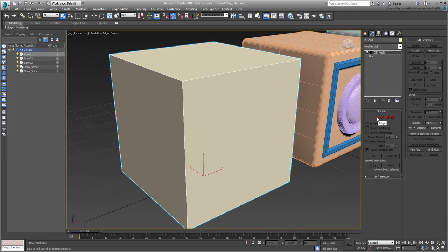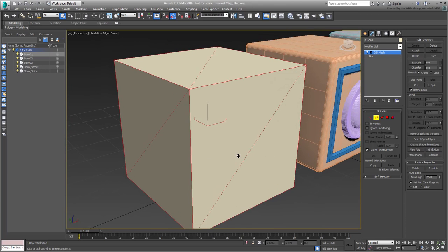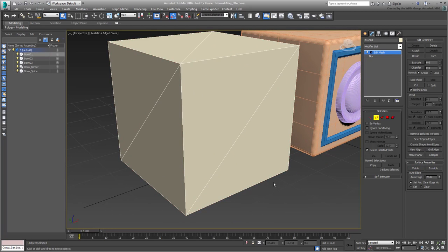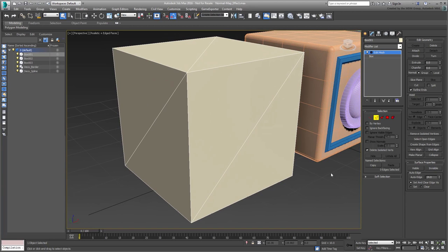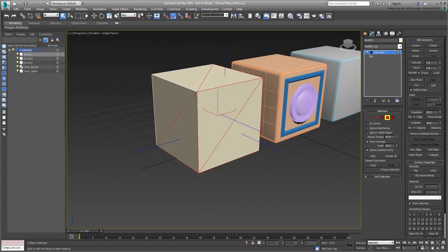Go into Edge mode and select all the edges. Note the dotted diagonal edges that are displayed. You may need a slight pan for refresh. Make these edges visible so you can study the face normals better. Go into Face mode and enable Show Normals. Note what happens when you select one or more triangular faces. Blue vectors appear perpendicular to their respective faces.